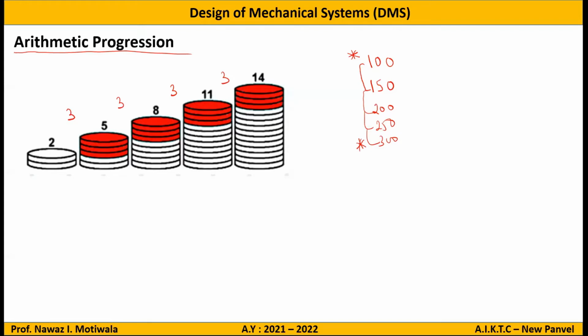Okay. Let me write a formula first and then we will verify whether my written formula is correct or not. So let me denote that common difference by A, which we normally do, or you can also call it R, common ratio, common difference. You normally read D, no problem. These are just alphabets, don't worry about that. So let us say if I write A, the common difference between the two steps should be n max, because I have this value, minus n min, divided by z minus 1.